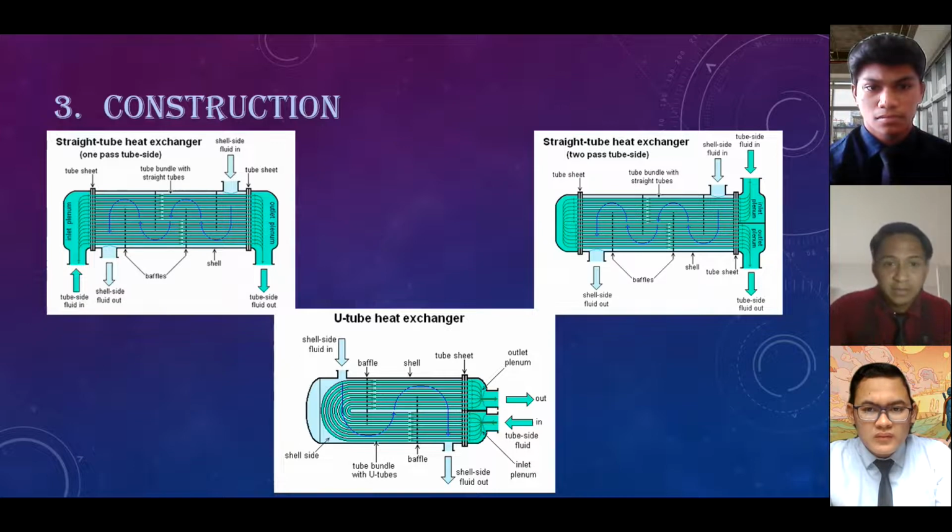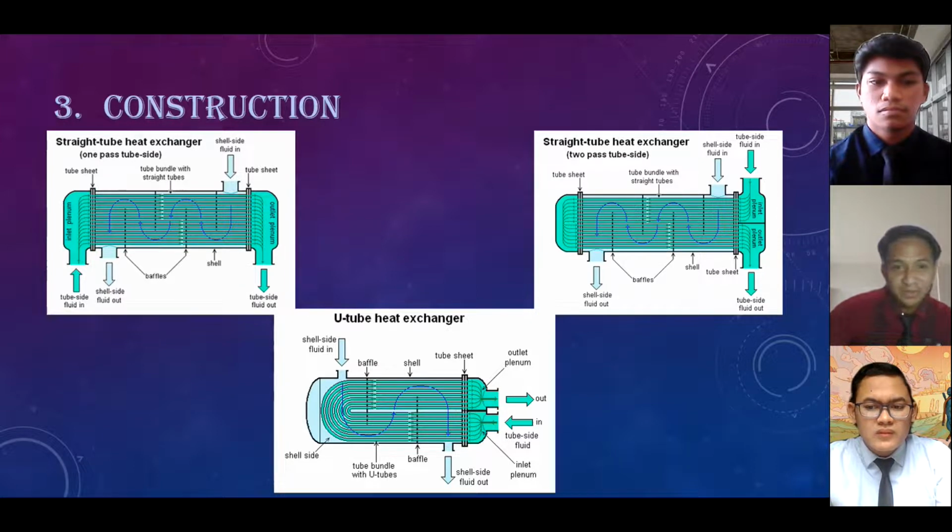In a nuclear power plant called a pressurized water reactor, large heat exchangers called steam generators are two-phase shell and tube heat exchangers which typically have U-tubes. They are used to boil water recycled from a surface condenser into steam to drive a turbine to produce power.